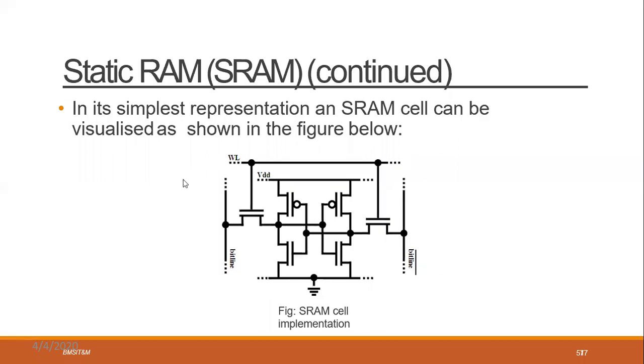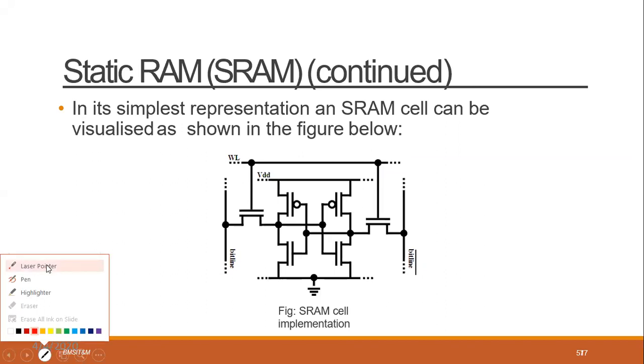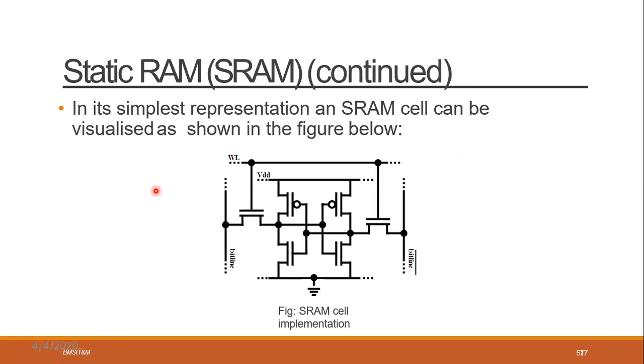Okay, in the previous session we discussed Little Endian, Big Endian, ASIC, memory, etc. So in Little Endian, what happens? The lower byte will be stored at the lower address, right? In Little Endian style, the lower byte will be stored at the lower address, and in Big Endian, the higher byte will be stored at the lower address, right? The different way of storing data into memory gives you the Little Endian and Big Endian styles.